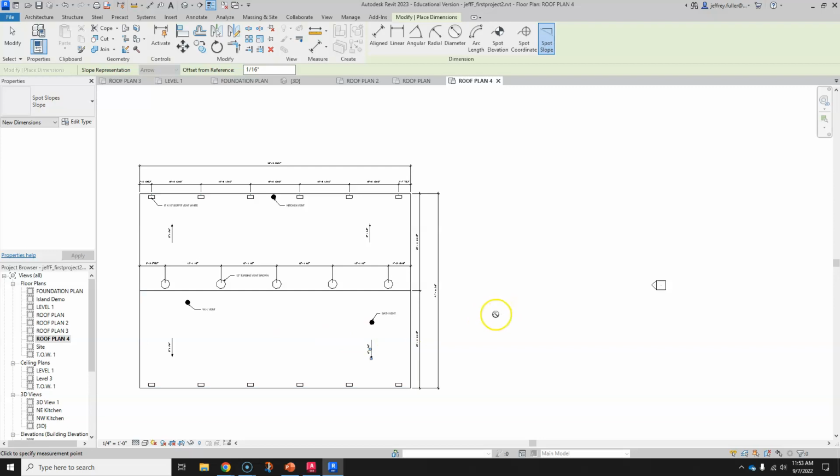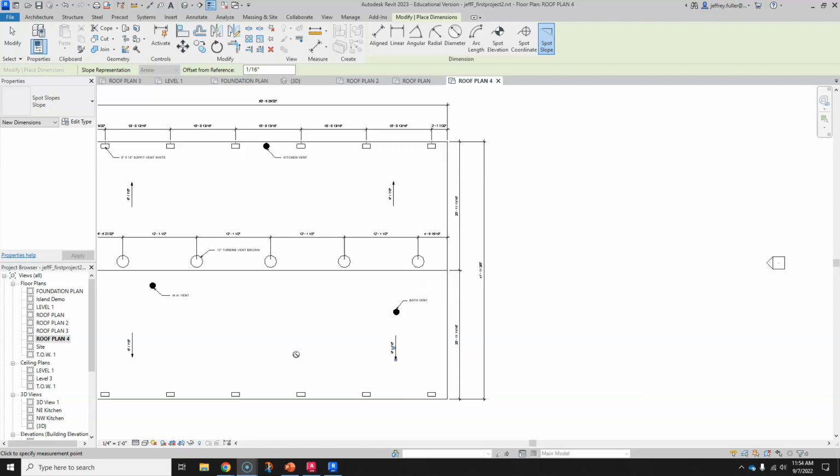Okay, so now I know that was a long video, but I believe we are done with the roof plan. Okay, unless you have other shapes in here that you need to label. Like if you have a roof, again, with those pop outs like we talked about, then we'll have to identify things like hip ridges or hip lines, and then your ridge lines, and then your valleys. Okay, so we have to make that very clear as well. Now on a gable roof like this, I really don't have to identify that, but I can.